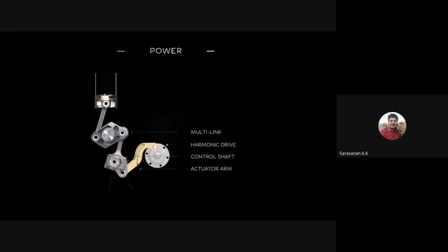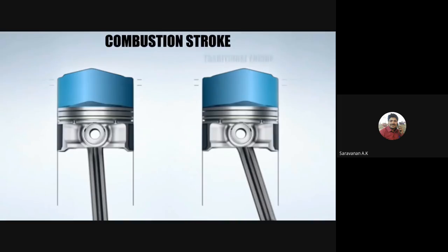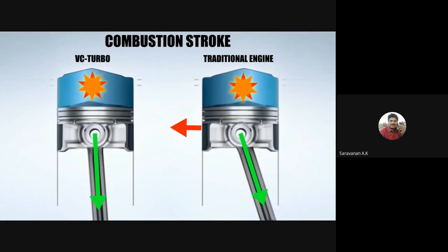Another unique characteristic of this crankshaft linkage is that it nearly eliminates side forces from the piston on the cylinder walls. In a typical engine, a piston will have a large opposing side force on the cylinder wall as it also pushes downward, rotating the crankshaft. This is because with normal engines, the connecting rod is at a significant angle when rotating the crankshaft.